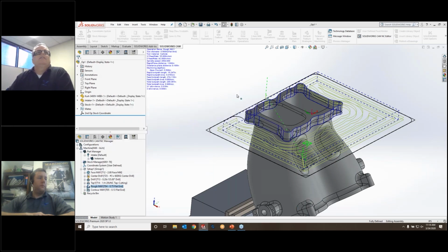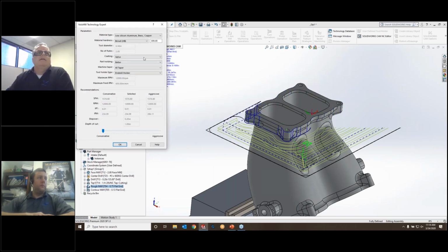So when I pick on this now, it's going to open a parameter page, right, on what it's capable of doing based off what I chose on the machine. There's a whole list in here. It shows aluminum because I'm already on aluminum, but if I was doing tool steel, alloys, carbon steel, cast iron, whatever the case may be, I just choose on that, right? The coating is a tool coated, uncoated, whatever the case may be here. And then the taper, right?